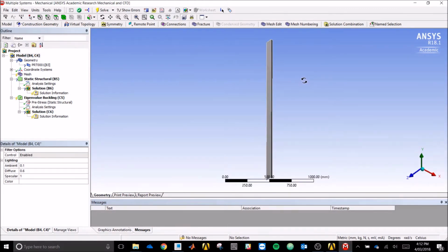Now this will be represented as a plate mesh. Now the utility of this is it allows us to change the wall thickness very easily rather than having to remodel the whole feature. If you also notice, under the static structural toolbox is the buckling analysis. So there is a bit more setup to be done before we can get the results.